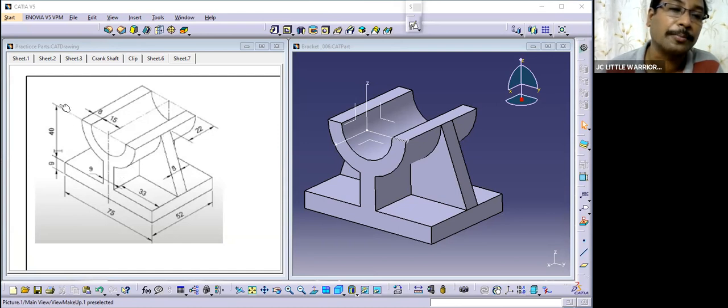The first step will be the complete block, and the second step will be removing this material, this side completely and this side completely, and then adding these ribs. There will be around 3 to 4 steps in that. But what we did now is take the complete front view profile, extrude it, and then add the ribs.